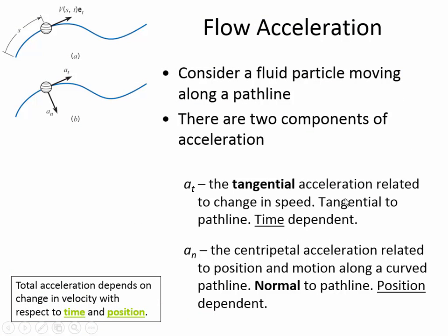All right, so there's acceleration with respect to position, and there's acceleration with respect to time. And remember, last time in class we were talking about steady flow and uniform flow, and how steady flow is when the conditions are constant over time. Unsteady flow, we watched the video of the flash flood in Arizona, where from one time to the next the flow conditions were different. Uniform flow is where the velocity is constant with respect to position, meaning that the streamlines are parallel.